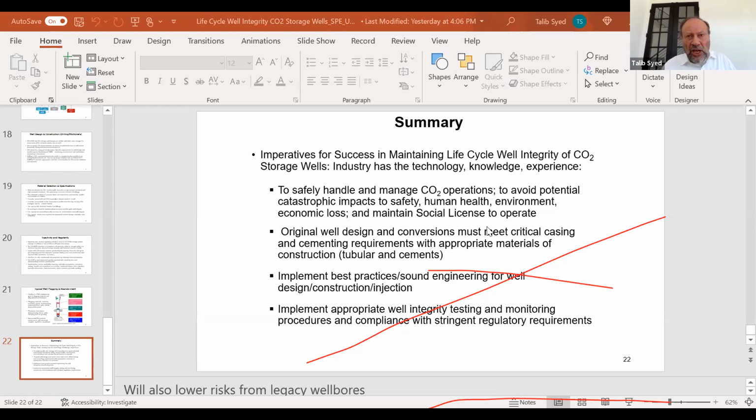And remember, every time there's a change in the status of the well, let's say you have a workover or well intervention, the barriers get impacted. So you have to go back and verify that the barriers are intact, and if they're not, you have to take steps to ensure that the barriers are there. For well integrity barriers, you always have to have a minimum of 2 barriers throughout the life of the well. And what is one barrier? During the drilling phase, you have the hydrostatic mud that is present, your steel, your cement. Anytime those barriers get impacted, you have to do a whole study, from a risk assessment, to make sure that they are restored before you can go on to the next phase.